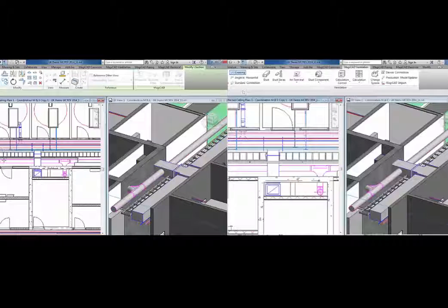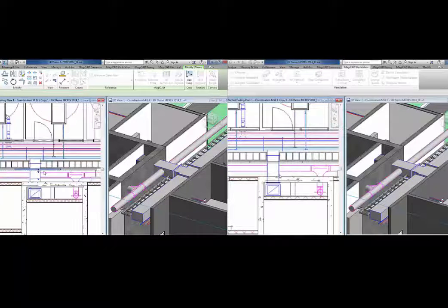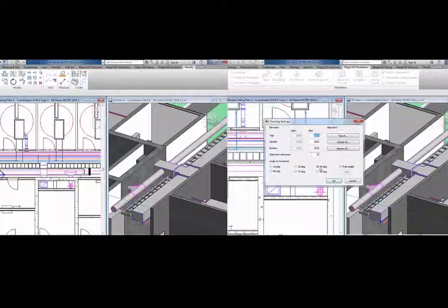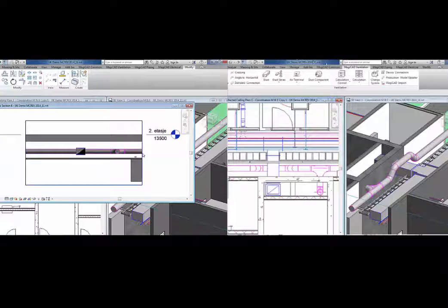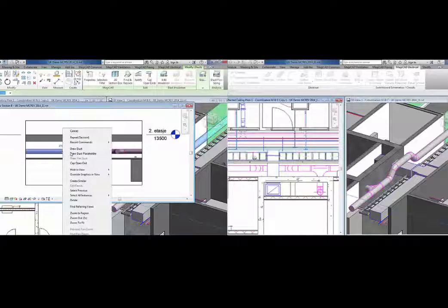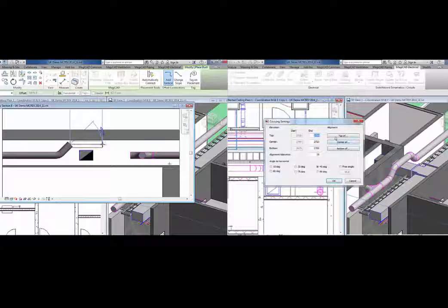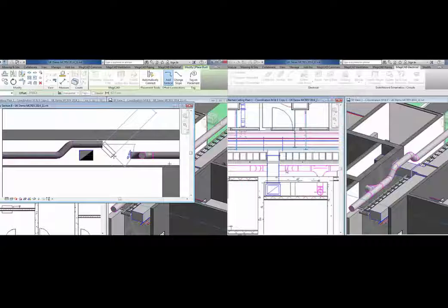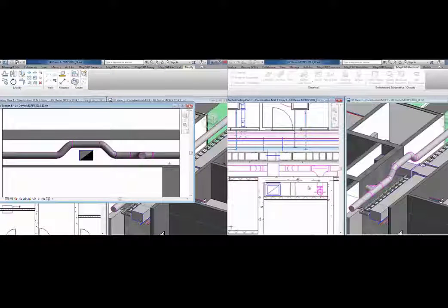This is the automatic crossing tool in MagiCAD. It saves a vast amount of time for technicians or engineers who wish to avoid clashes by rearranging the services once they have been put in. As you can see there on the right hand side, it's MagiCAD's functions, which are just popping the offsets of cable tray and ductwork automatically over other objects at the specified heights in relation to each other, and with a tolerance between the services as defined by the user.